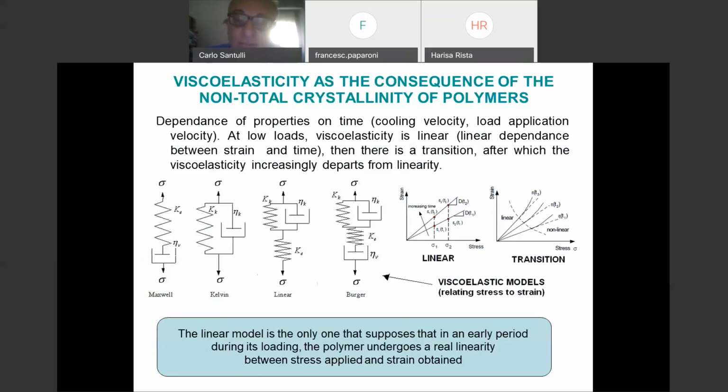In fact, you can see that with polymers, with plastic, we do only limited rotating devices because we have a limit into that. There are some more rotating devices you can see with glassy plastics. For example, the first example you can see is the CDs, which are made of polycarbonate. In fact, they don't suffer a kind of deformation in rotation. You wouldn't make a CD with a rubbery plastic like polyethylene, because it might be the case that the deformation would grow with frequency in an uncontrollable way, which leads to the breakage of the disk.